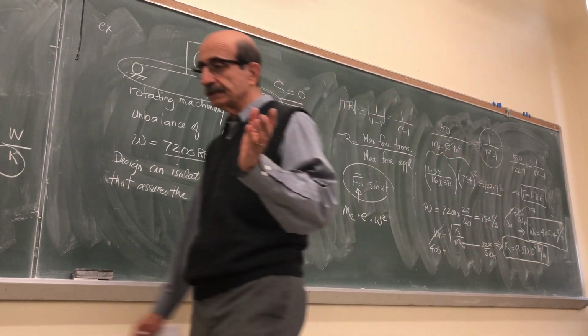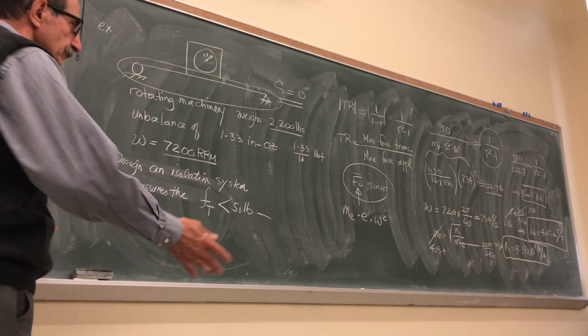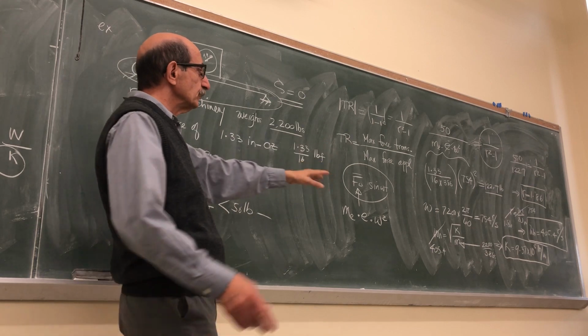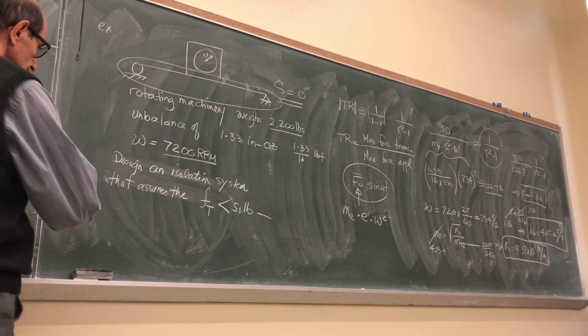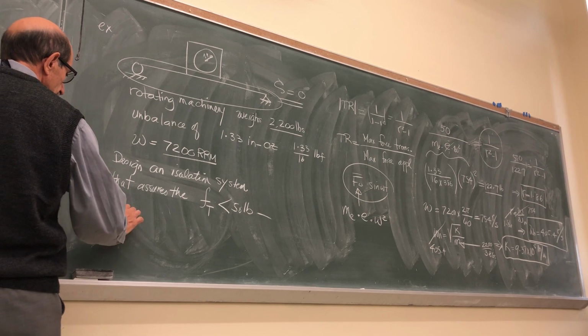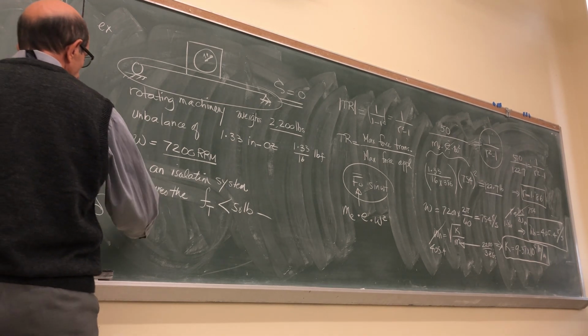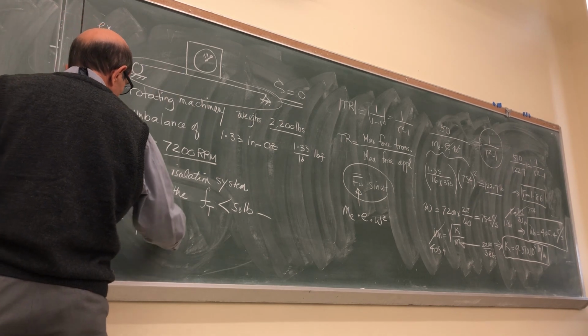However, we are not done yet because, as I said, vibration isolation is a give and take. You want to make sure that if you have such a stiffness, you really don't get a lot of static displacement. So you need to evaluate the static displacement for that beam, which is basically the weight of the system divided by that stiffness.